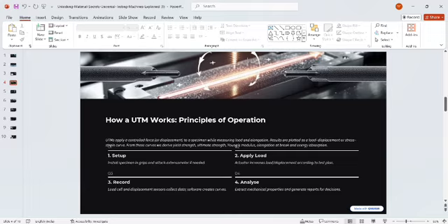For the setup, install the specimen in the grip and attach an extensometer if needed. Let us watch the diagram: here we fix the specimen we need to examine, and add the extensometer if we need it. Next, apply the load to conduct the test on the specimen. Next, record the readings: we collect the data using the software and create a curve.